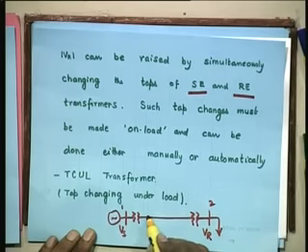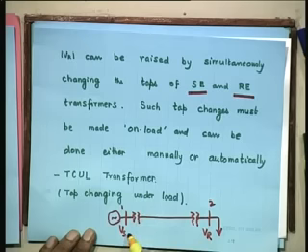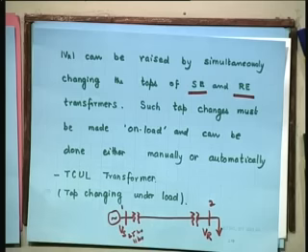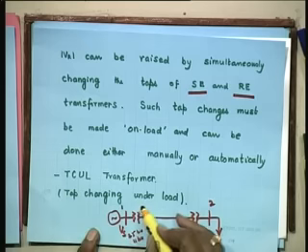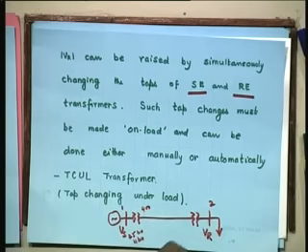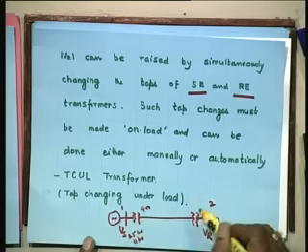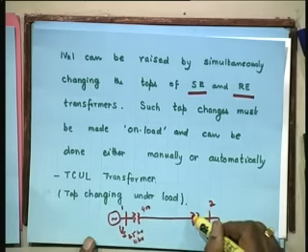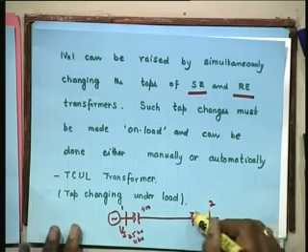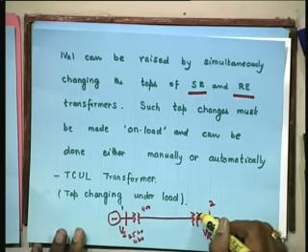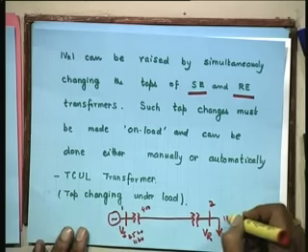This Vs gets converted to 400 kV. This may be 25 kV or 11 kV. Generation is always at a low kV because of insulation problems, cooling problems, economic problems, and so on. So, when this 25 kV becomes 400 kV, you can as well make it 410 by taps here on the sending end. So, that is 410, and when it gets reduced, it may become 400 here itself. That is what you wanted, and then 400 can be lowered to 11 kV, where the load is.